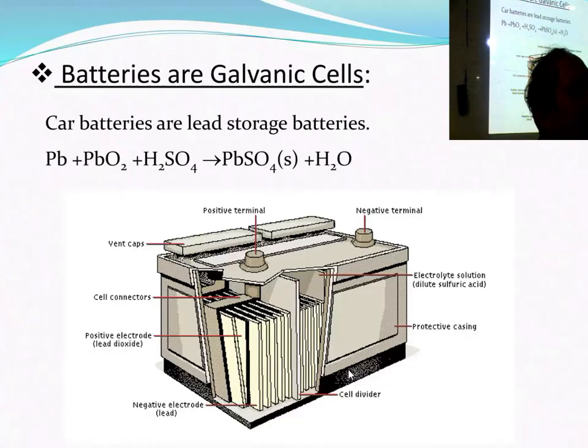Normally 600 cycles is very common for a small battery, but for a larger battery it can be longer, because a larger battery can withstand more. Why? Because you have a bigger plate, no? So if some portion is physically damaged, other portions can be utilized. That way it will run much longer.